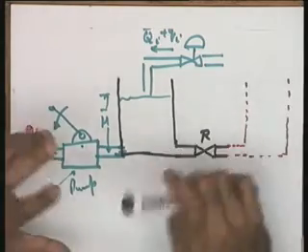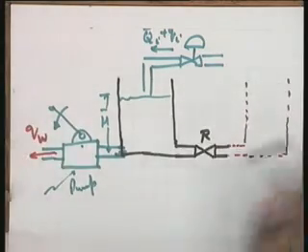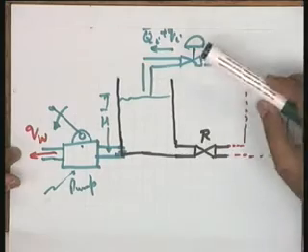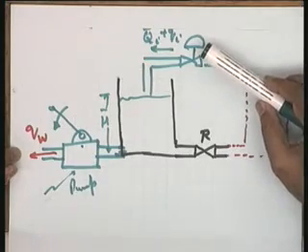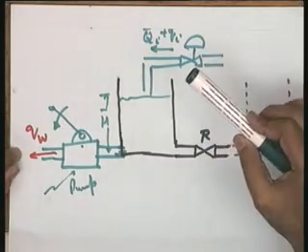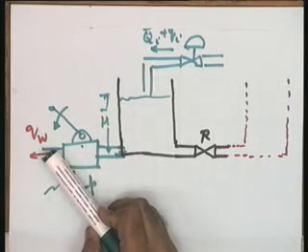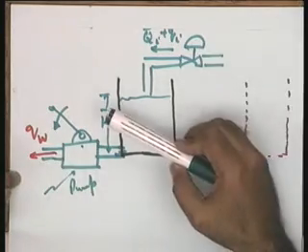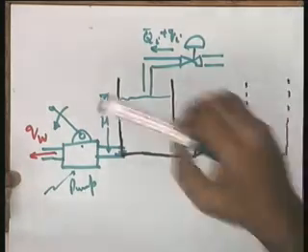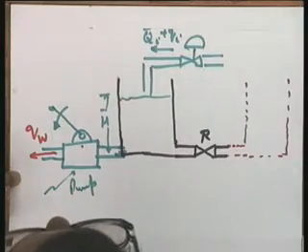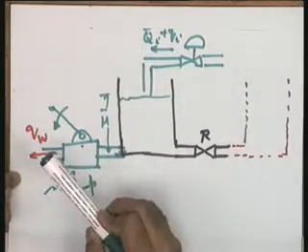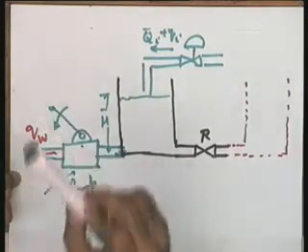In setting it into a regulator control problem, I am calling it a disturbance. So control action is to reduce the effect of this disturbance to 0. It means as soon as you have demanded QW, the control action should set the height H to the preset location immediately. So you see that your purpose, this is a flow which you have demanded.